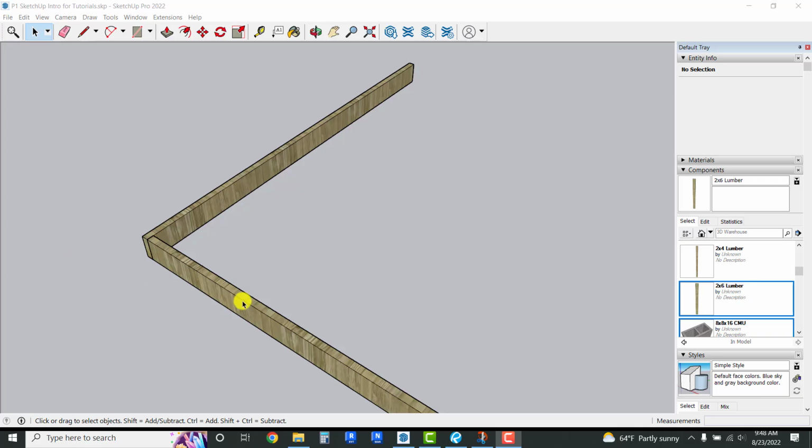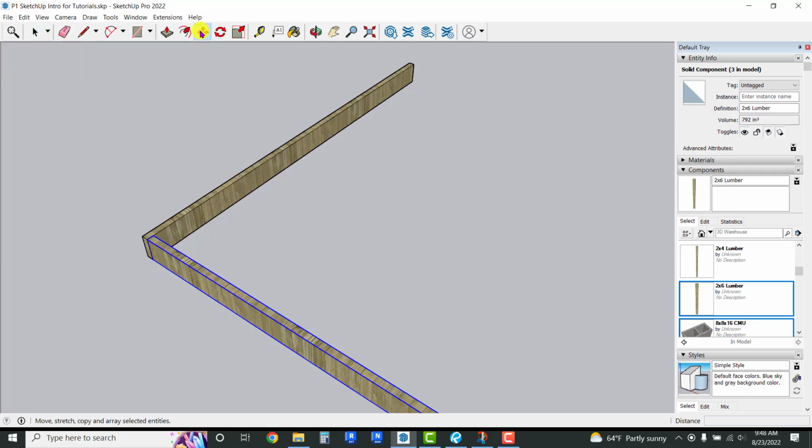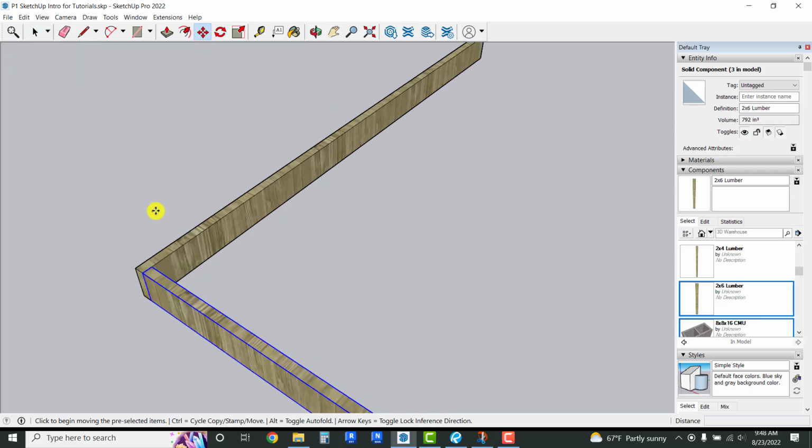So I'm going to select the first joist in the series, choose the move command, and here one edge or the other doesn't necessarily matter because 24 inches from this edge over is going to be the same distance as 24 inches from this edge over. It will measure the same, but I'm going to say this outside edge because that's really where I would pull my tape from.